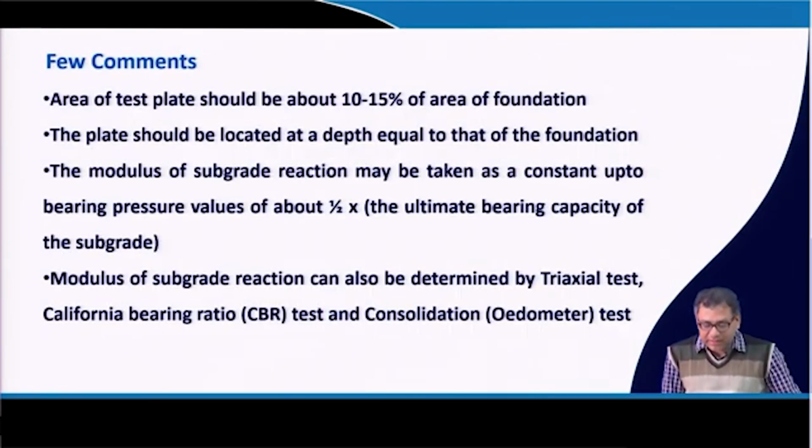So, if you use this correlation, then you will get the k value for a particular foundation or particular soil, where the foundation and soil interaction are both considered. Now, a few comments: when you do the plate load test, your plate size should be taken such that at least 10 to 15% of the foundation area is covered by the plate size. Okay.